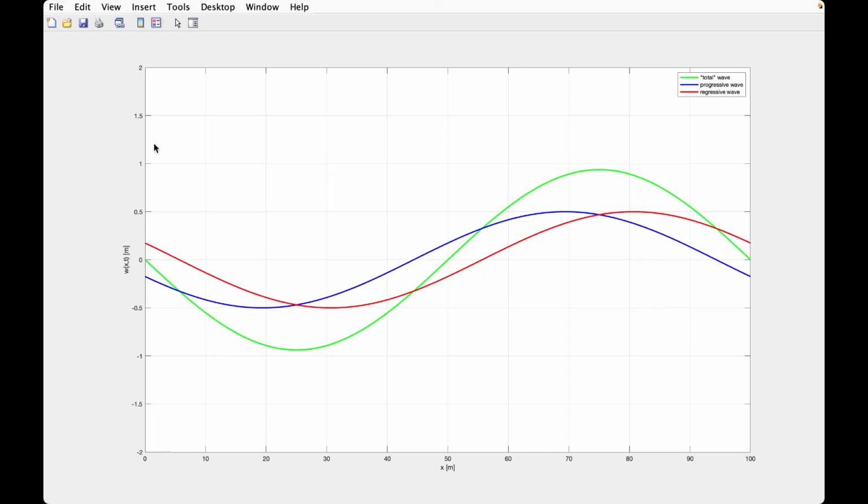And so if you are looking at the representation of the different harmonic functions that are consequent of the infinite ways of movement of the tensioned cable, we recognize that the wavelengths of the subsequent shapes are just lambda 1 divided by n. So the nth mode, having a frequency n times larger than the first, has a wavelength that is lambda 1 divided by n, but where lambda 1 is not L, it is 2L.